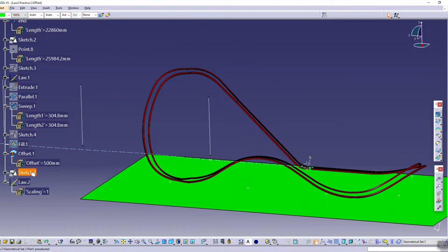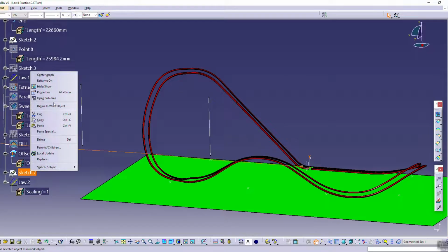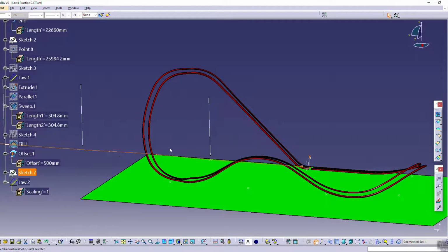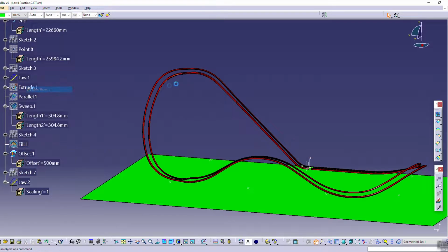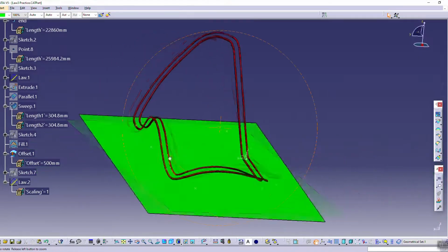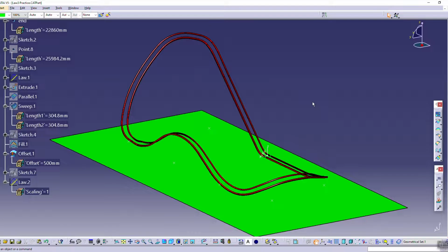So you can use another sketch where the center line is 0 degrees and you go up and down to bank right or left. So you can use another 2D sketch to control a 3D shape. So now another question is cross ties. How do you do cross ties? Well, there is not a really good or easy way that I know how to do cross ties in CATIA.